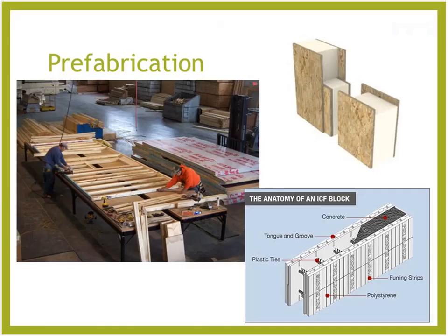And then also continuing with wall systems is the concept of prefabrication. And so some of the benefits of prefabrication are, you have a manufacturing process, so you're weeding out design flaws right there in the shop. You've got your specs. You can give them right to the shop, and they can design a really good wall system. The other thing about prefabrication is usually shops tend to be a little more savvy on reduction of waste. So a ton of waste can be diverted from the landfill and usually can be reused right on site within the manufacturing process.